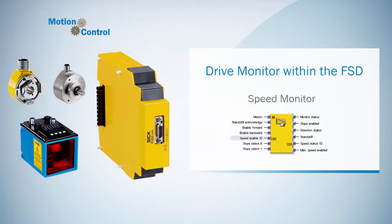With the optional input speed enable ID, you can select the permissible speed limit. If the current speed at input motion is higher than the selected speed limit, the output monitor status goes low. At last, there are the optional inputs slope select 0 and slope select 1. They make it possible to select between 4 different slopes, which monitor the transition from one speed to a lower speed.